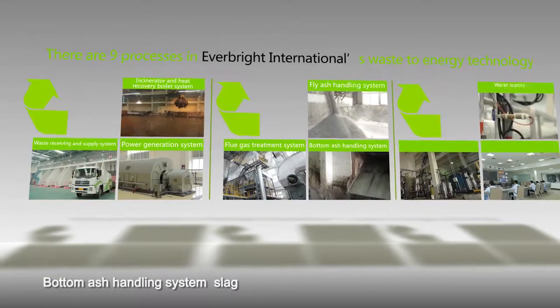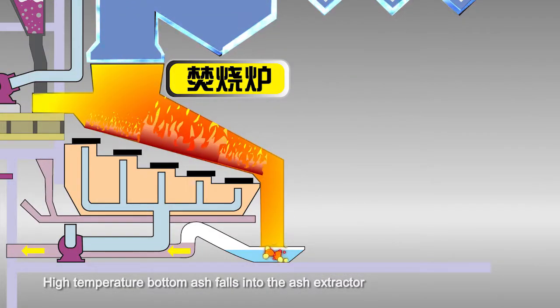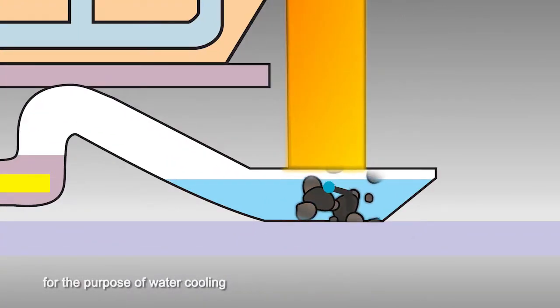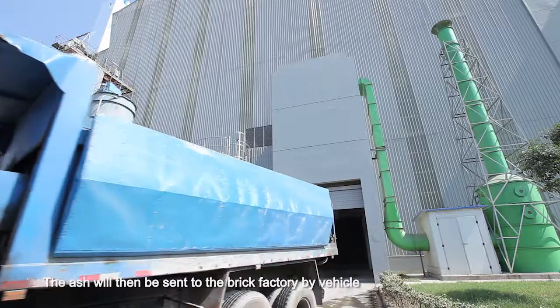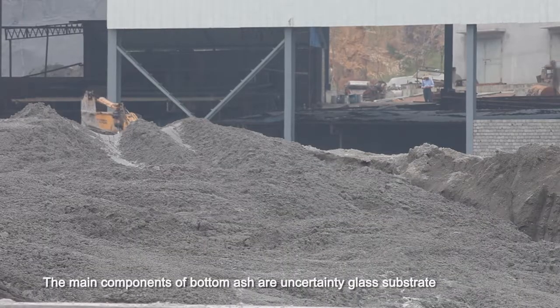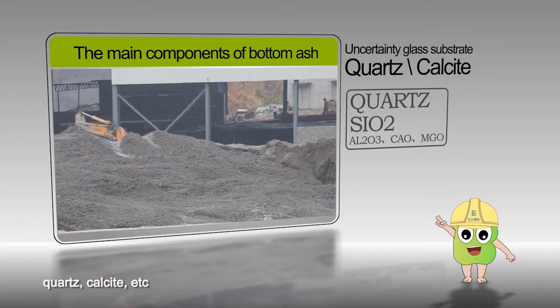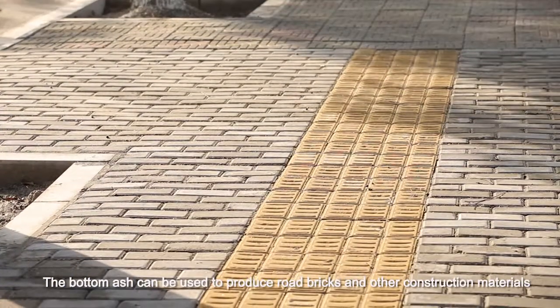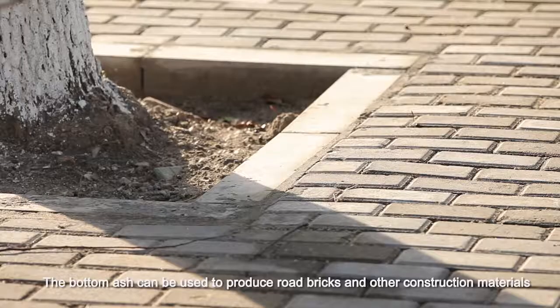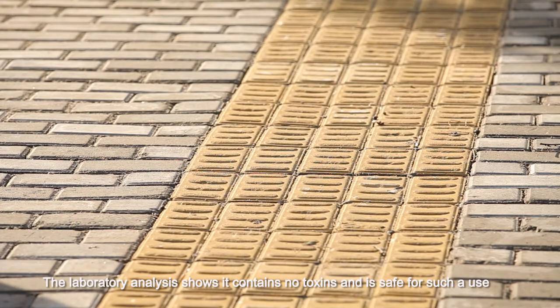Bottom ash handling system, slag. High temperature bottom ash falls into the ash extractor for the purpose of water cooling. The ash will then be sent to the brick factory by vehicle. The main components of bottom ash are glass substrate, quartz, calcite, etc. The bottom ash can be used to produce road bricks and other construction materials. The laboratory analysis shows it contains no toxins and is safe for such a use.